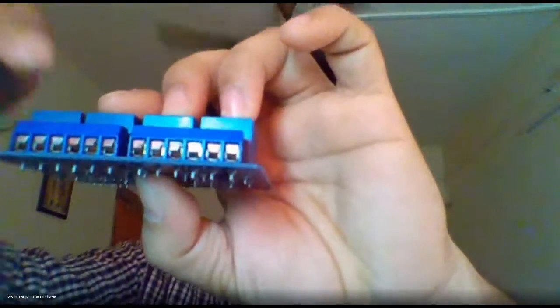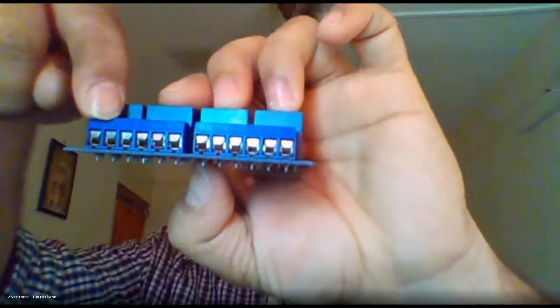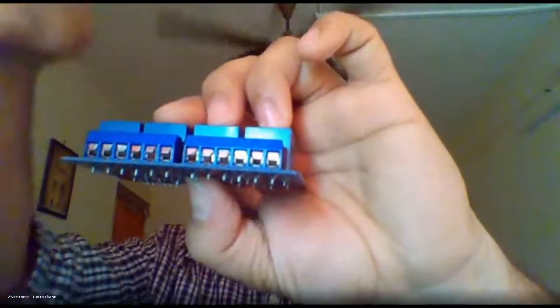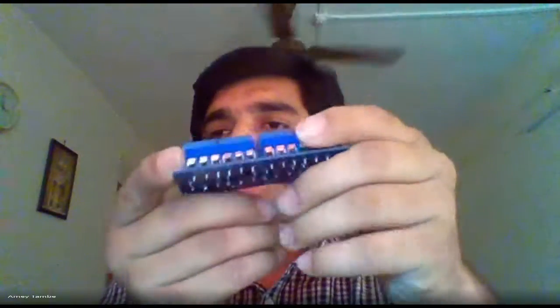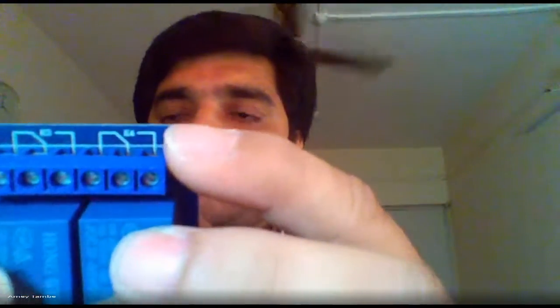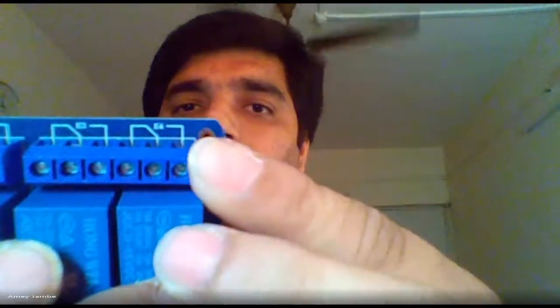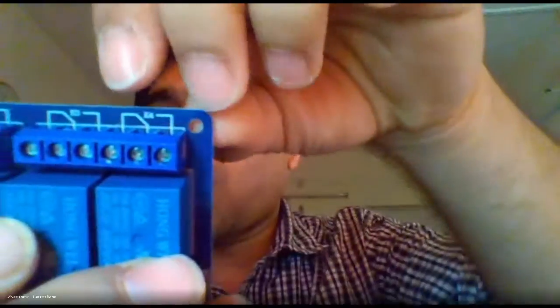Now these relays typically come with a configuration like you can see over here. Each relay has 3 ports. The middle port is the common port. This common port will be attached to the main power supply. And then we have a normally open and a normally closed port. It can be shown in this kind of diagram. So if participants are from an electrical background or have a little bit of electrical know-how, then they can understand this circuit diagram.